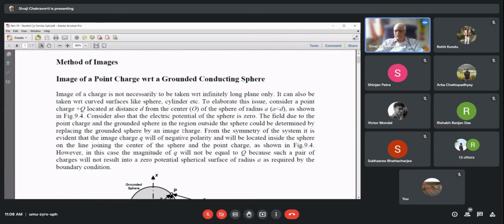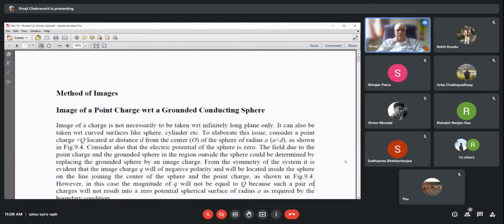Any idea? Well, many of you will probably say solid state switches. I don't disagree, solid state switches can be used, but what is the voltage rating of one solid state switch? This you should tell me. If you take one, say, silicon switch or selenium switch, what will be its voltage rating? Because these are the information as an engineer you should have.